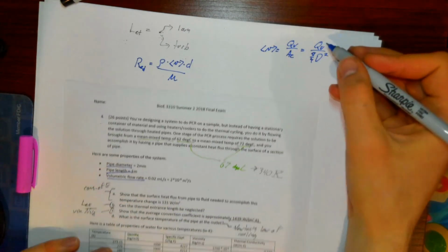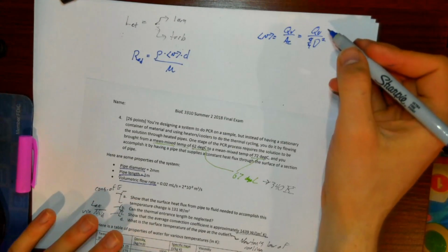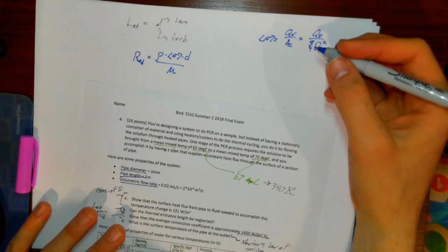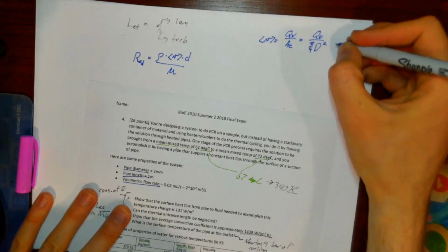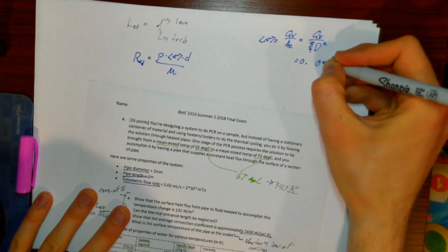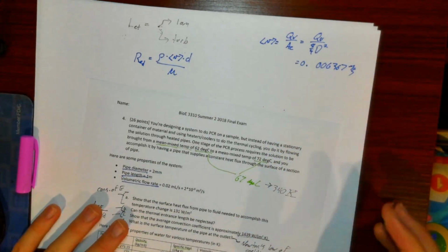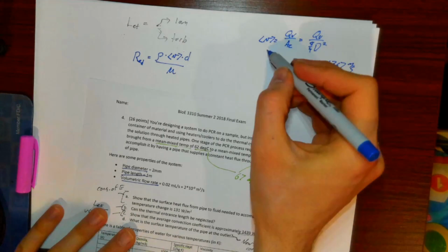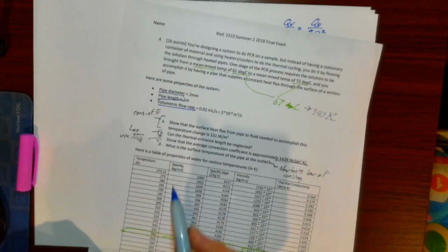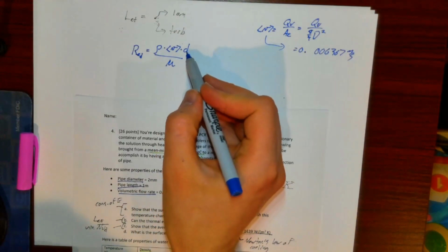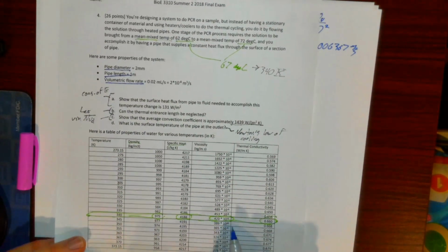So you plug in the volumetric flow rate, that was a given, and the pipe diameter, that was a given, right? When you plug it in, you end up with, I forget what it is, like 0.006367 meters per second or something like that. You can check me on the numbers, but that's what I had here. So this gives us all the information we need for velocity. We have density, which we just got from the chart right here, the pipe diameter, which was given to us, and viscosity is something we can read off the chart as well.